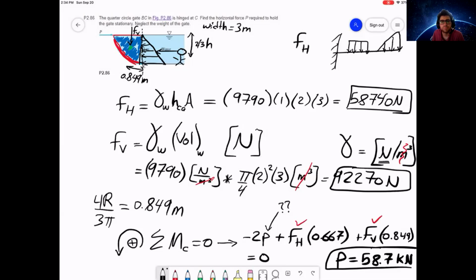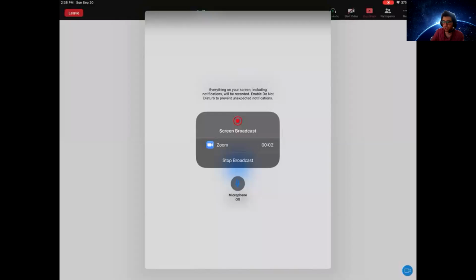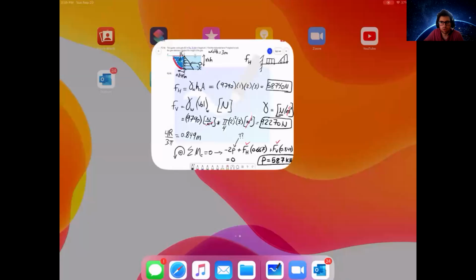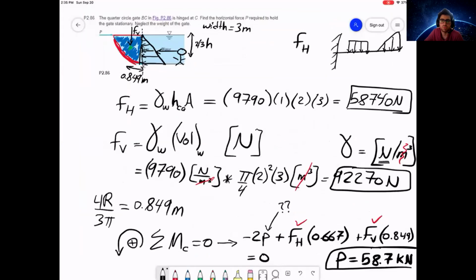Yeah, that's a lot nicer than using the formula. This one is easy because it's just a flat surface, and I know the pressure distribution is going to be a triangle. And where is the centroid of a triangle? Back from statics, I remember it's 1/3 from the bottom or 2/3 from the top. So I can go with that. Or if I have a complex geometry, I can use YCP and XCP and be done with the problem. I don't have to think about it.